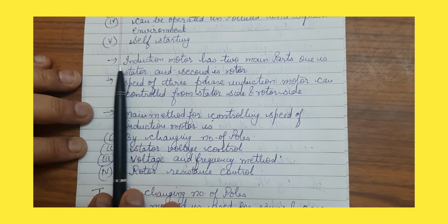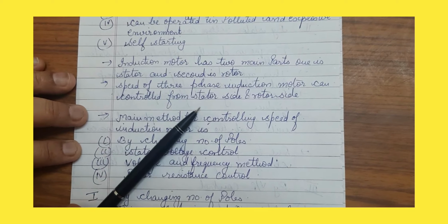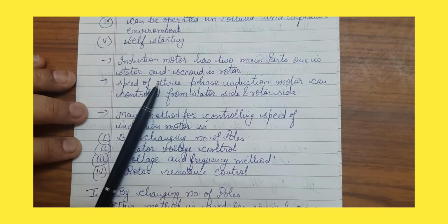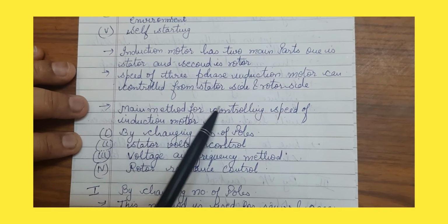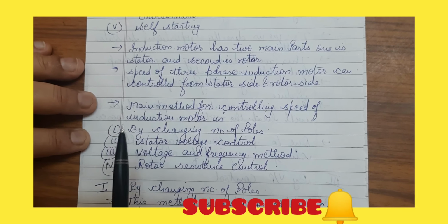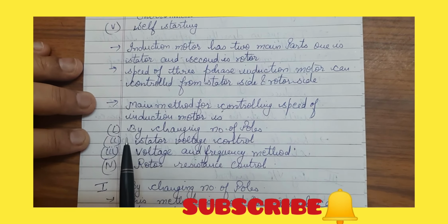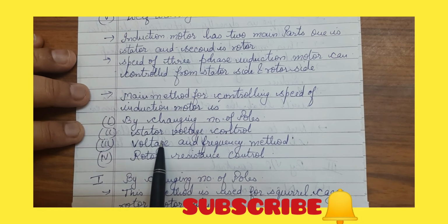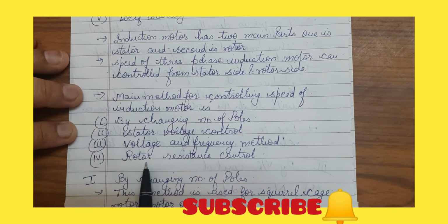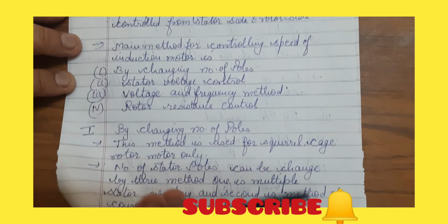For any motor there are two main parts, that is stator and rotor. Like this, an induction motor also has two main parts, one is stator and second is rotor. The speed of the three-phase induction motor can be controlled from the stator side and the rotor side. The main methods for controlling the speed of an induction motor are changing the number of poles, stator voltage control, voltage and frequency control, and rotor resistance control.